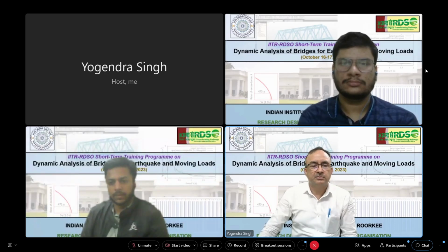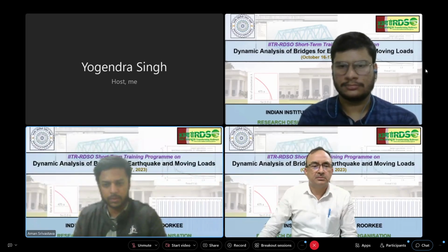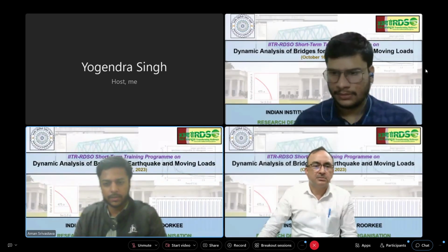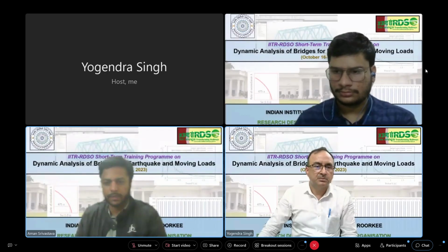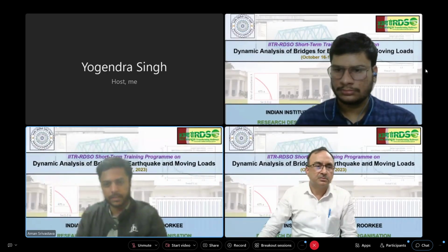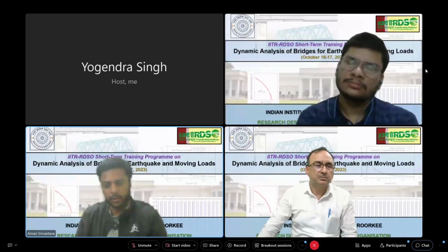We have a new question. While modeling elastomeric bearing in our project, we apply stiffness of elastic link. The stiffness in two horizontal directions is in the range of 2000 kilonewton per meter. While we run the response spectrum analysis, base shear reduces due to less bearing stiffness. I want to know the process of modeling the elastomeric bearing.